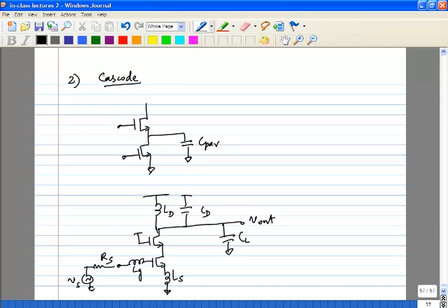And in many cases, this is probably one of the best kinds of amplifiers. We saw that the common source MOSFET has a pretty low Fmin. If you look at the Fmins you can get from this, we looked at the MOSFET 2-port parameters, right, with the common source. So you can get very low Fmins, 0.6, 0.7, somewhere around that, even for a long channel. And now you add the cascode, you have got rid of your stability problems, or at least to some extent. Your common source has a lot more gain. So this is pretty good.